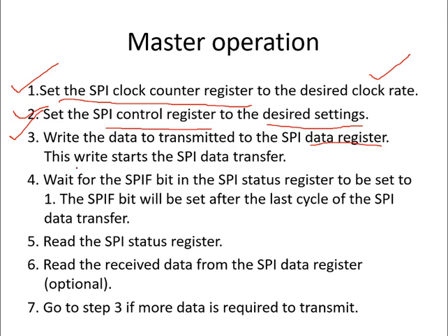This write immediately starts the SPI data transfer. It is the same as your UART. Whenever you write the data in the UART register, it will automatically start transferring the data. Similarly, whenever you put the data in the SPI data register, the transmission of the data will start.